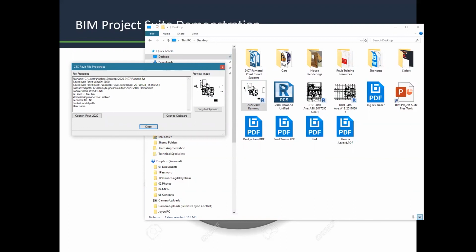So this will report the year version that it was created in. Of course, if you've got Revit 2020, it is doing that already. If you open it up from within Revit 2020, it will now tell you what year that content was created in. But this lets me do it right from the Windows environment. If I've got a folder set up or I'm looking at an archived project, I can figure out which version it's using without Revit asking me if I want to update it and me saying, no, because if you update a file, it updates the only version of that. I'm sure none of y'all have made that mistake.